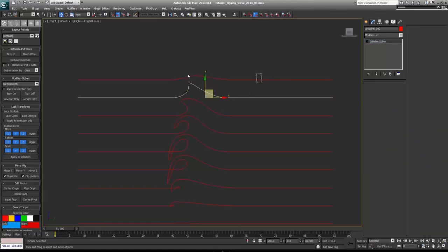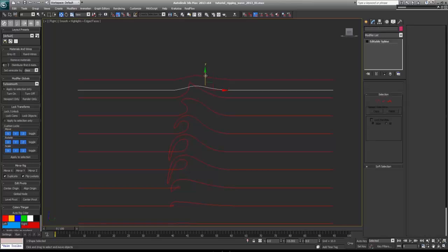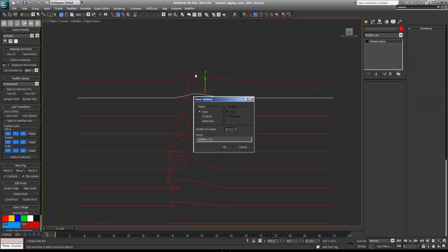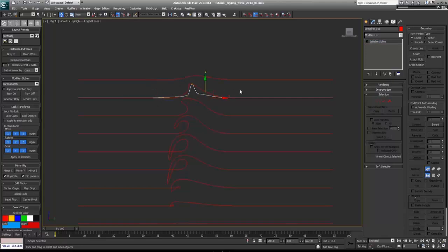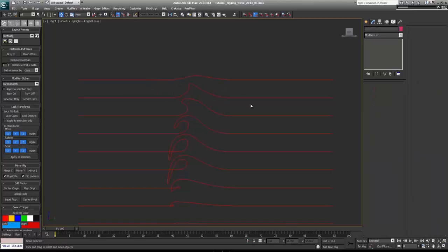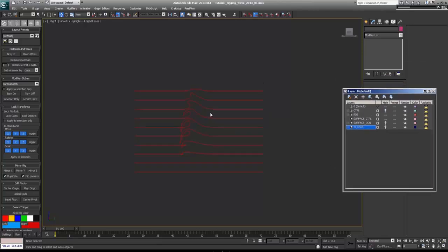So the way that I did that is I created the first one, which is just this really simple shape, and then when I was creating this one, I did a shift drag to clone it, and then adjusted the points from there, mostly moving vertically just to make sure it's a natural move, because if your points get shifted down or moved over too far, you'll see that happen while your morph is happening, and it will probably have some undesired effects. So once you have those curved profiles traced, that is what's going to drive this entire effect.